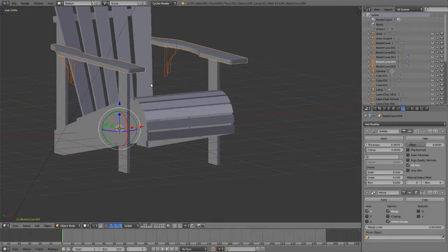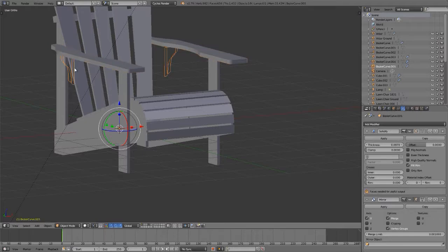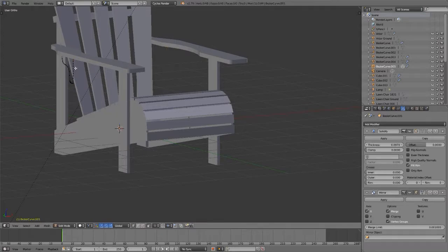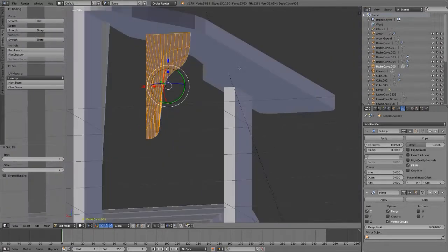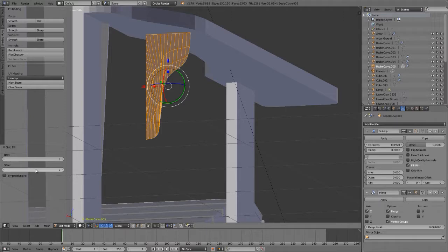Oh, it doesn't have a face. Right, okay, so right-click, select it, and now let's do that fun, funky thing, which is tabbing into edit mode, selecting all of the edges, and Control F to grid fill, and have a look at the results. T to open the tool shelf that will give us access to changing things as we need to. Simple bending. Control spacebar hides and reveals your transform manipulator.